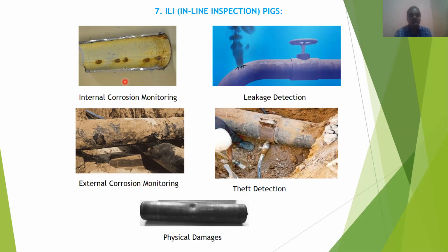This oxygen will try to attract the metal, ferrous, Fe. Then it will make a pinhole over a period. So in such cases, if you run intelligent pigging as per the requirement, we will come to know the thickness available circularly, every millimeter.